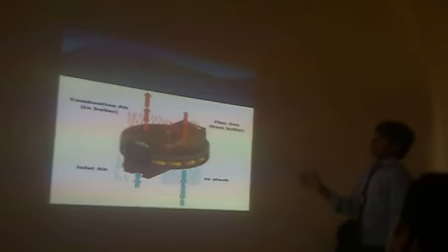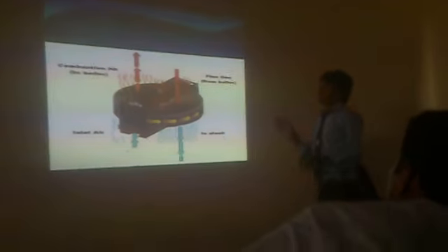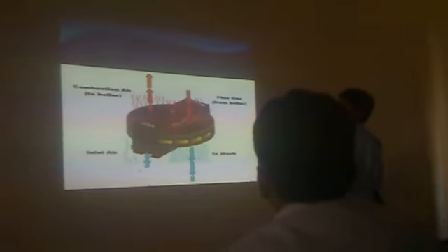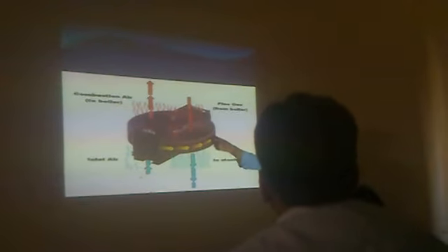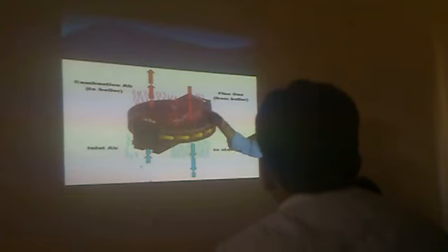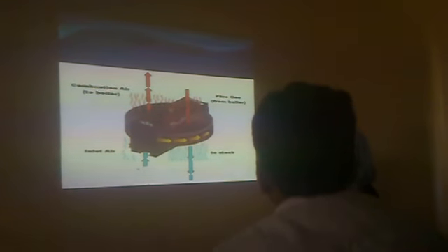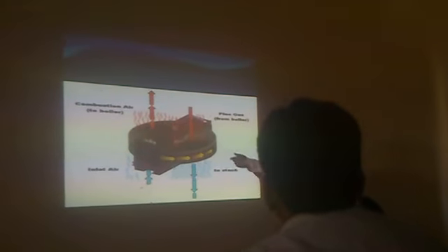So this is the air preheater. Earlier I said that before sending atmospheric air into the boiler, we have to heat that air with the help of the air preheater. In the air preheater there are tubes, and in the tubes the atmospheric air is filled and the flue gas strikes those tubes, so the atmospheric air is heated. It is heated up to 120 to 130 degrees centigrade and then sent to the boiler.